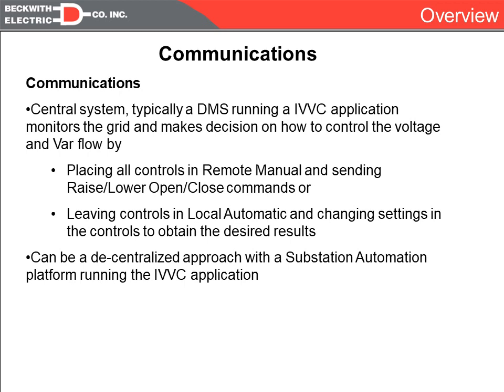So with a centralized approach, we typically see a SCADA Master or a distribution management system, DMS, that will be polling all the devices from switch capacitor controls to feeder regulator controls to line regulator controls to LTC controls. It will also in all probability be pulling data from protective relays and downline reclosers. And from this data it will do some sort of analysis and then send out commands to individual controls to have them operate.